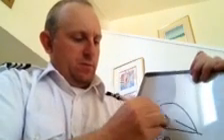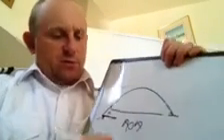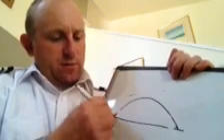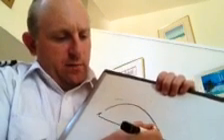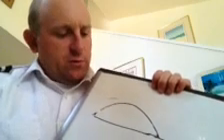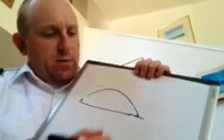Next thing we want to talk about is the camber of the wing. The amount of curvature of the upper surface of the wing is going to determine how much lift we generate. So in flight, our flight controls are used to modify this camber.